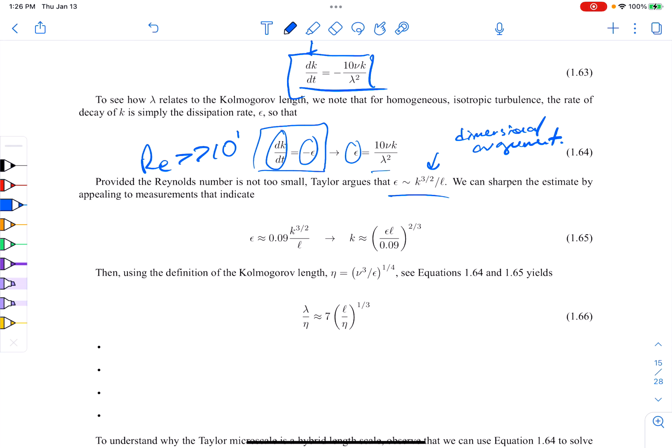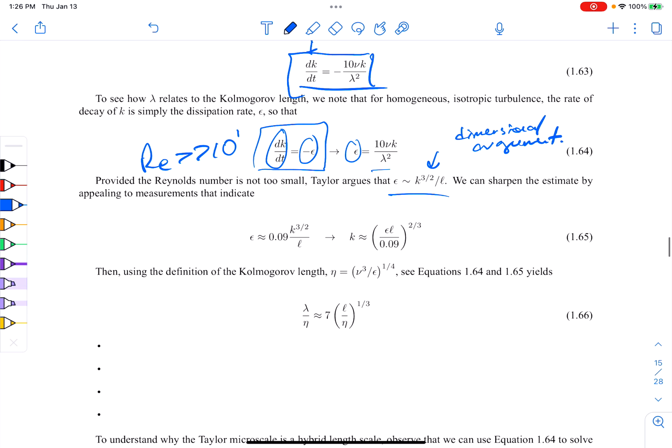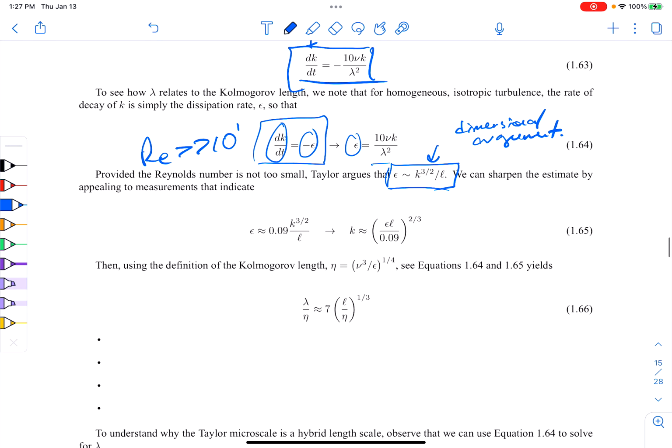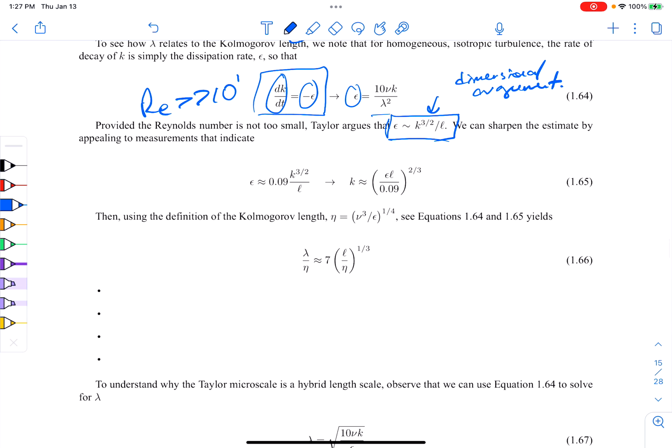And it so happened that it works well when comparing with experiments. And so that's a powerful tool, which we might look for in the future. It's not really estimating the small scales of turbulence yet, but kind of fitting in a few parameters. This was based on dimensional analysis. By fitting a coefficient, it corresponded really well with measurement data, and that coefficient was 0.09.